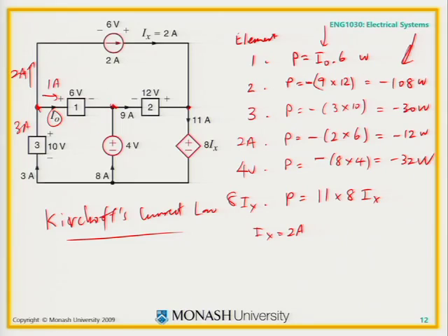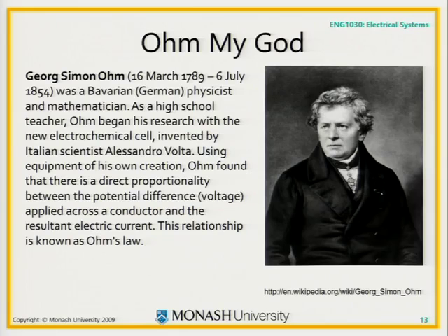So you've got the current here, 11 amps, and this value, because it's a voltage source, must be in a unit which is not dimensionless. So it's actually 8 ohms it would be. The unit of this constant would be ohms, it's not dimensionless. So that's why it becomes a voltage. Very good spot though. Nobody's ever spotted that one before. Good on you.